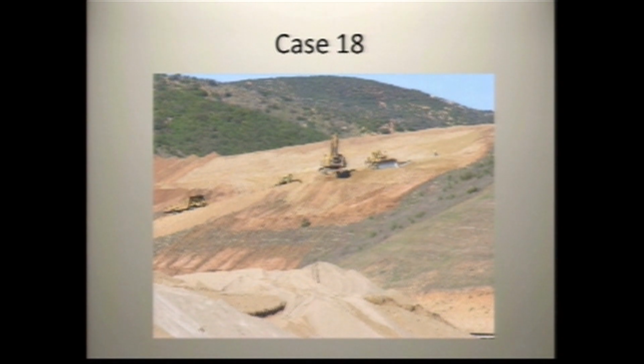Same thing on a slope like this, right? I mean, if you went out there and said, hey, these guys are actively working the slope, they're probably doing some sort of a buttress or something back up. If you go out there and say, hey, I want straw wattles on that slope, you're going to be laughed off the site, or probably worse than that, actually. So it's not practical, it's not functional. If it's going to rain tomorrow, you could still have the same thing in place, right? The downstream sediment controls, and hit this thing with EarthGuard, polyacrylamide, something like that to get you through that one storm and be prepared then to start work the next day again. But doing nothing violates your MS4 permit, violates the construction general permit.